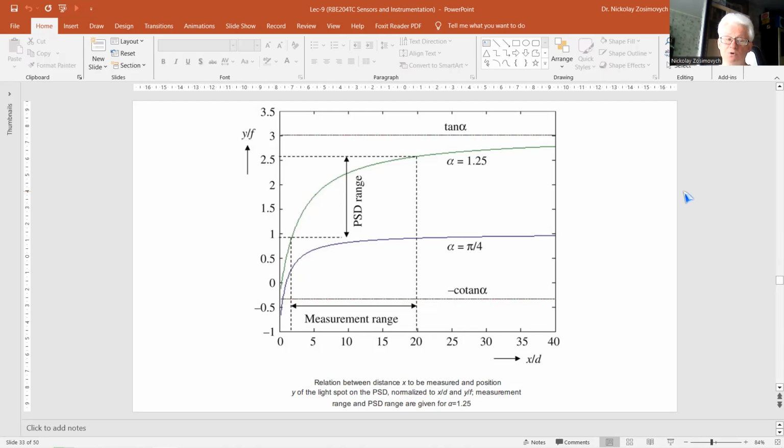A more serious problem is the low S/N ratio due to a poorly reflecting surface material, a slanting angle of incidence, or simply a too large distance. By using multi-sensor techniques and signal averaging, the accuracy can be improved by a factor of 10.